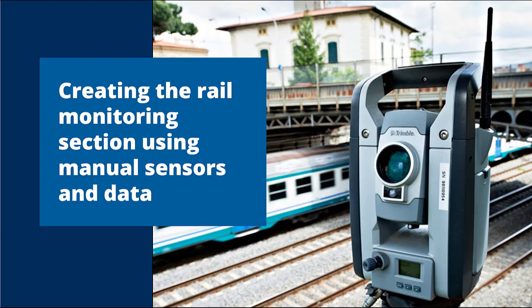To see the rail module in T4D, a license must be available, and you have to have at least one sensor created. For this purpose, we're going to use manual sensors and manual data import, and I created a track file and sensors next to it, as well as the measurements which can be applied to those sensors to have some data in the charts. The data is in the local coordinate system.